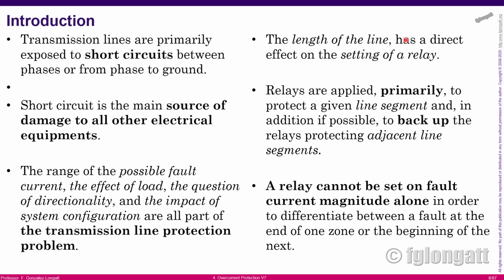Something very important is that for transmission systems, the length of the transmission lines has a special effect, okay? Because it defines the total impedance involved in the short circuit, I mean, limiting the short circuit from the sending terminal to the short circuit point. I will discuss a bit more about this later, okay?